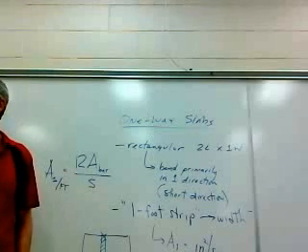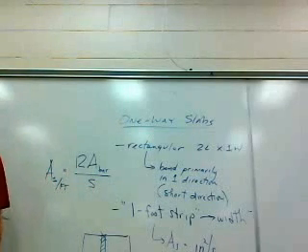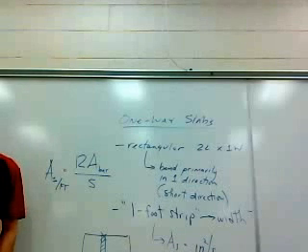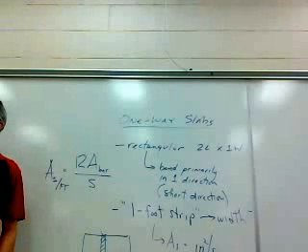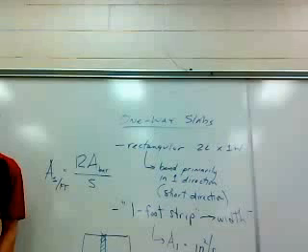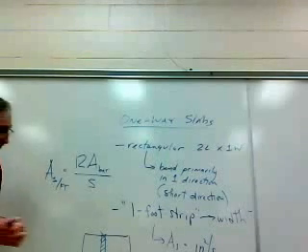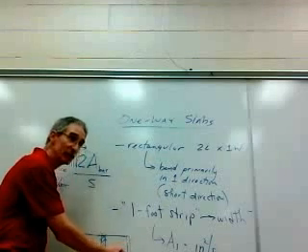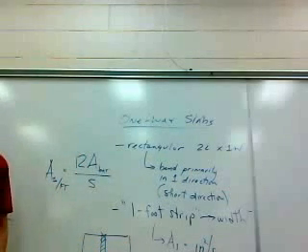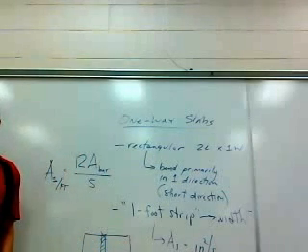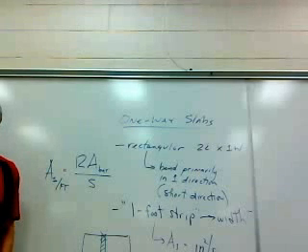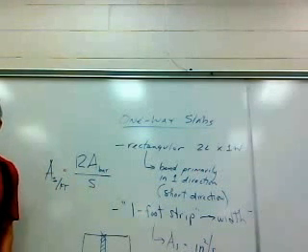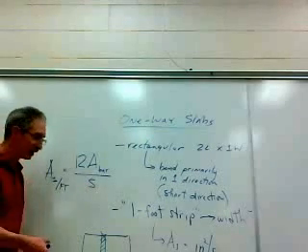Would you typically run your rebar the short distance? In a one-way slab, the short distance will have the bending steel in it. Okay. Now there is steel that runs the other way, probably too. But what's that steel running the other way for? Not compression, temperature and shrinkage. Okay?